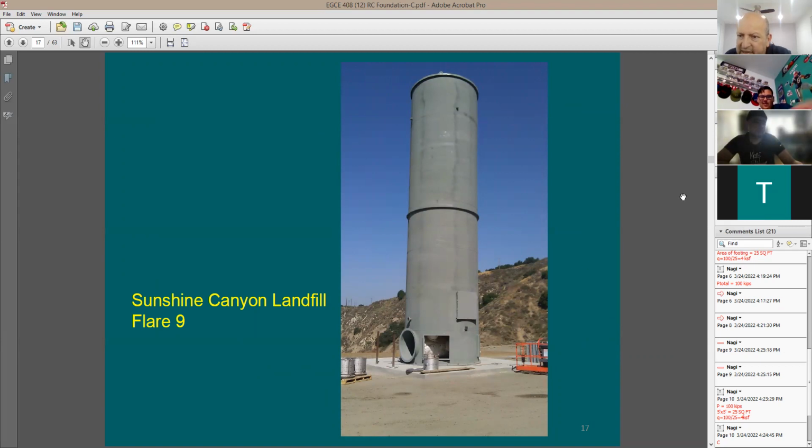Now, in a case like this, I'm gonna have the loads on this footing: a vertical load coming from the weight of that thing, right? Plus, I'm gonna have maybe some earthquake forces acting like this, or maybe some wind loads. So the gravity footing that we have discussed, which supports only dead load and live load, is exposed to only vertical load. But a footing like this is going to be exposed to a vertical load and some moment, acting in this way. So when the wind blows in this direction, this footing is going to be supporting some moment here.